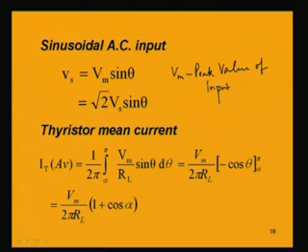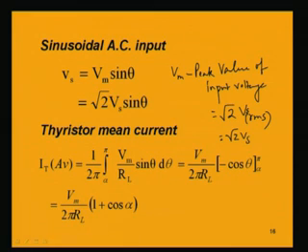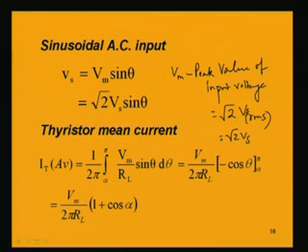and omega t equal to theta. Again, the maximum value or peak value of the voltage is equal to root 2 into V RMS. The root mean square value, if we consider, which is say Vs, Vs signifying the root mean square value of the AC voltage, which is the average quantity which is used to express an AC quantity, and root 2 times that RMS value will give you the peak value. So, in another way we can express it as root 2 into Vs into sin theta.